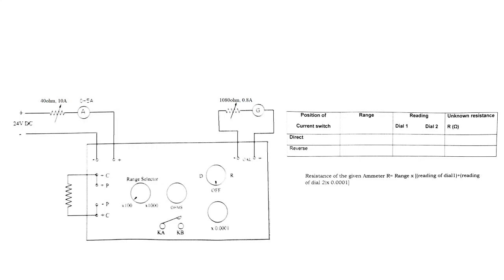Anyway, we start to increase the step of this bigger knob with a greater multiplier, and at the same time we will close the switch KA KB each time, and we go for watching the galvanometer deflection as in the Wheatstone bridge. At the point at which the galvanometer needle crosses the zero, we again switch back and start to step in the knob with 0.001 deflection, and we will bring the galvanometer to completely zero. This is one set of experiment.